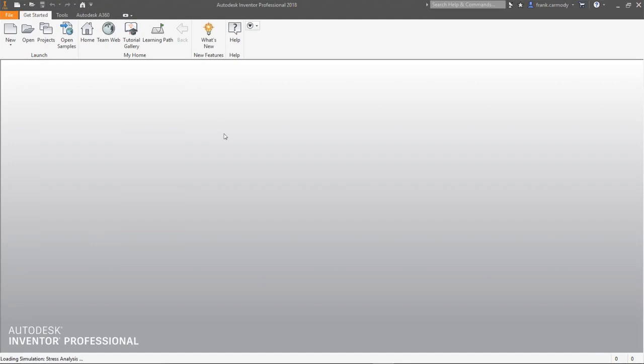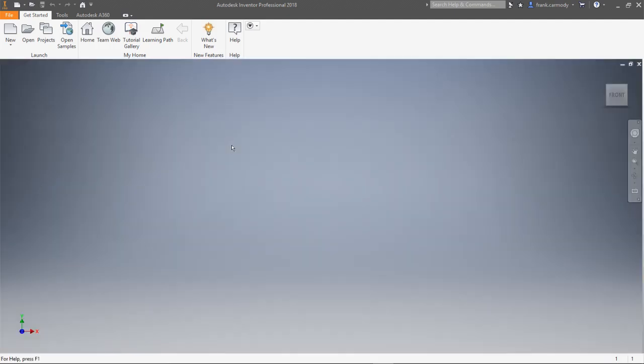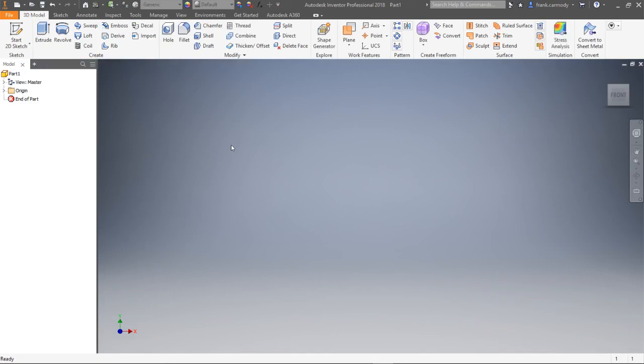It's kind of similar to if you make a project in video editing software, where you have all your clips in a folder, and then you put them all together in the video editing software. But if you move those clips anywhere, everything goes awry. The same thing is true with Inventor. So what you want to do is store all of your IPT files in one folder with the assembly, with the drawings, and then never move them.